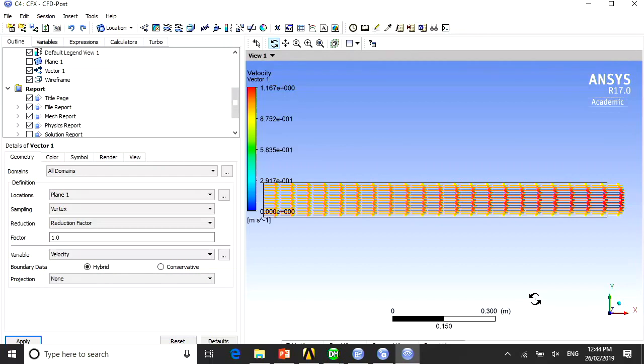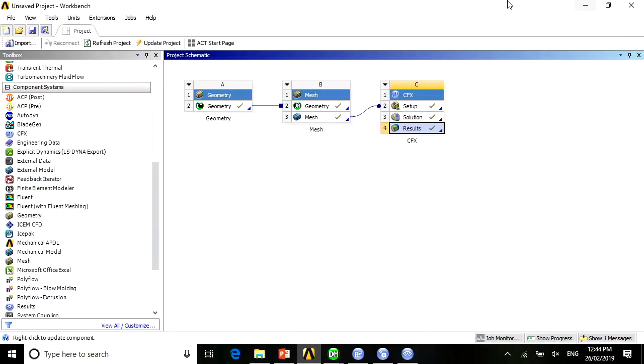Now, I'm going to go back, and I know that this is turbulent at the moment. I'm going to solve a laminar flow now to show you the difference between what you got now, the velocity profile, and the laminar profile. Very straightforward. I'll go back to the pre-processor.